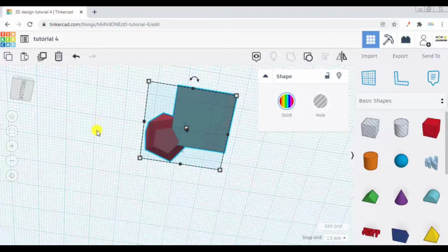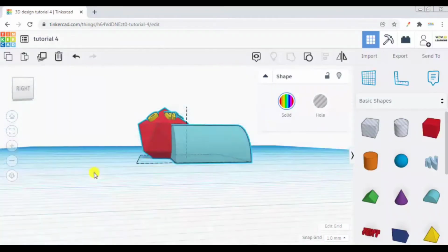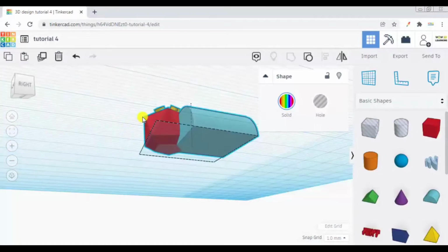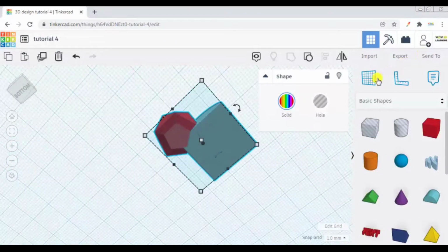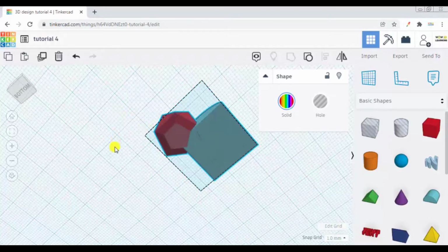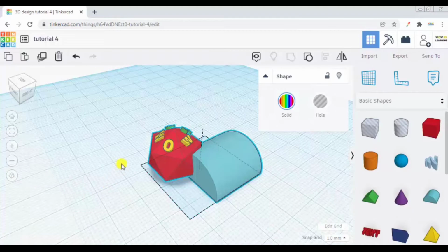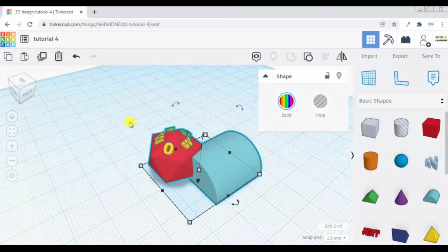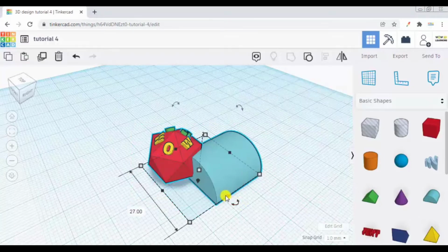The model from the bottom should be plain on the printing bed if we are giving the command for 3D printing. So this is how, if you have any object whose bottom you want to flatten out, you can make use of a work plane, select a bottom and click this box onto that to eliminate the extruded portion which you don't want to print. So let me hide this object now. I will select everything, press Ctrl+H.